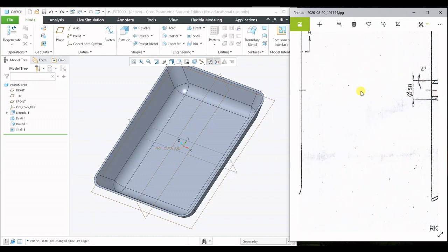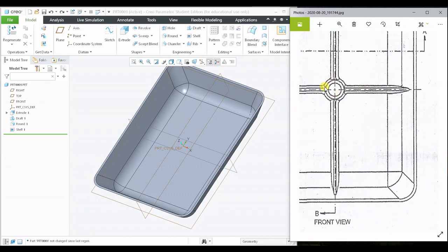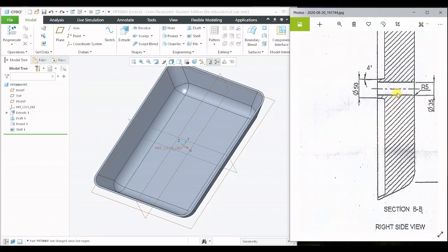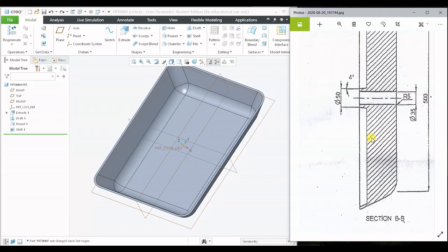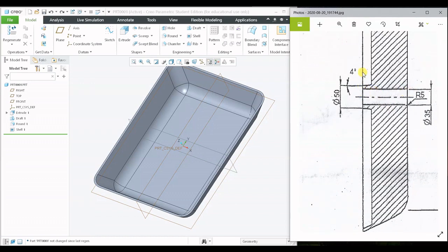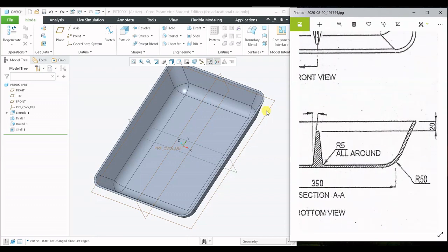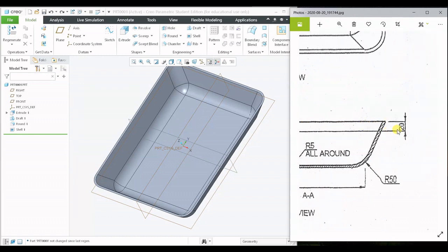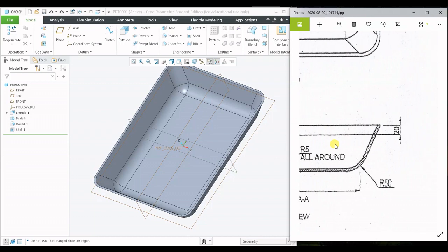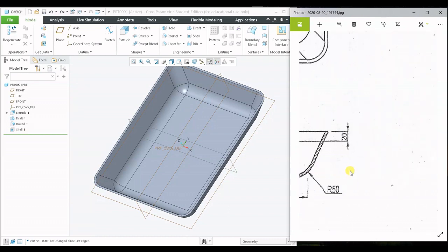The hole is created on a circle which is extruded over here. So we have to create an extrusion of a circle, and the height of the circle what we have to create from here will be the height of the wall, because it is observed in the right side view that the hole length is almost closer to the wall length, and this shaded region is the rib. The rib is created a little lower than the outside wall, so the distance of the rib will be from a distance of 20 units downwards.